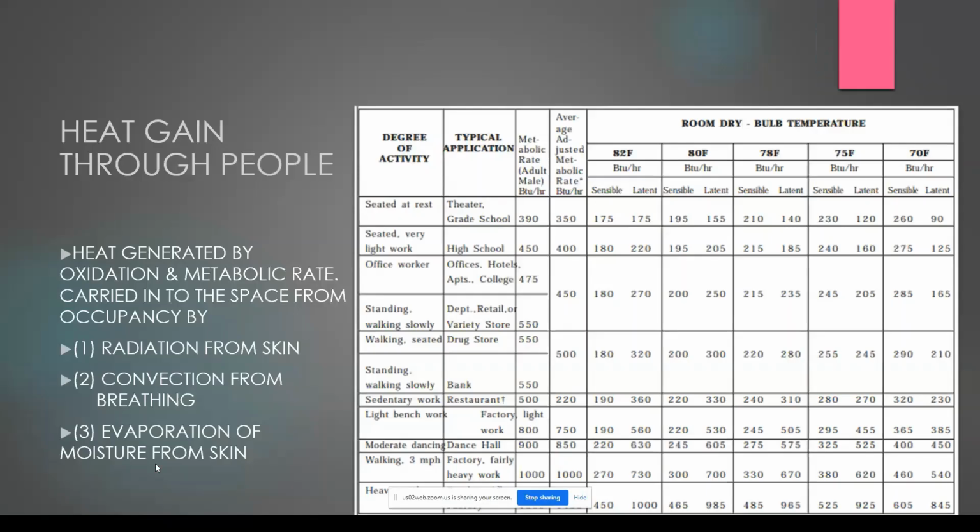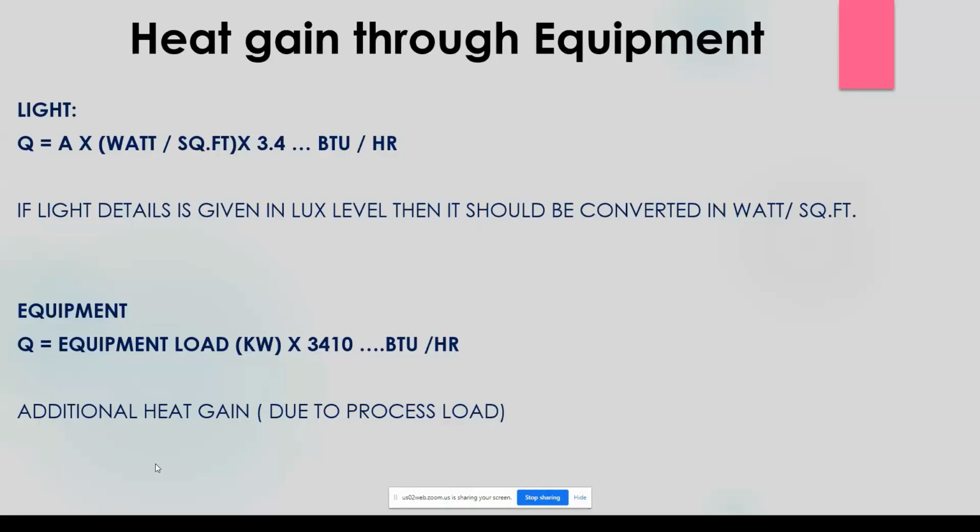Gaurang, when you talk about heat gain through these equipments, can you also guide him about the server and UPS and battery load, what he should consider? Yeah. See, we can have various equipment, and if you do not have the details available with you, we can use the data book, because it has tables for various equipments, and for the servers and other things.